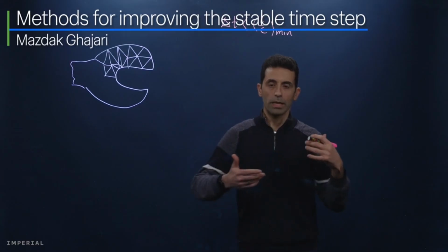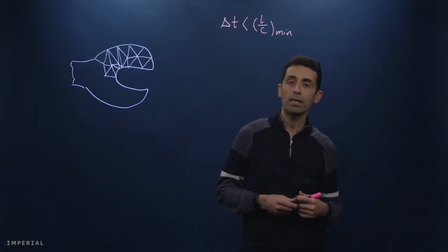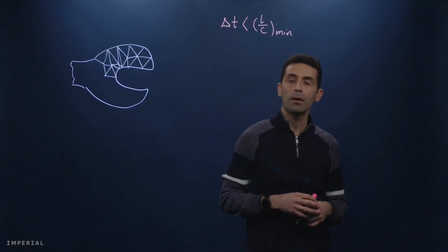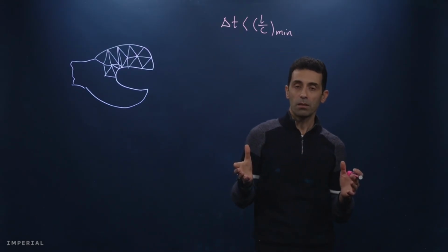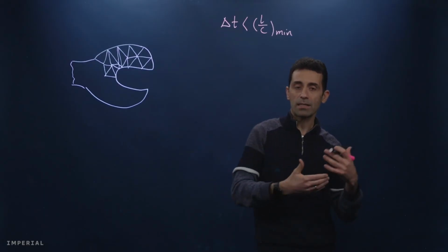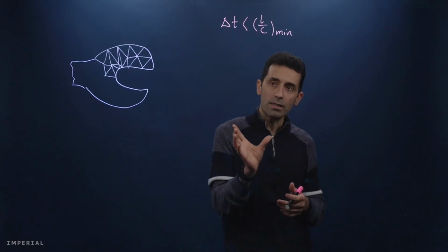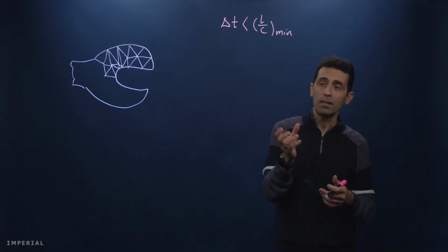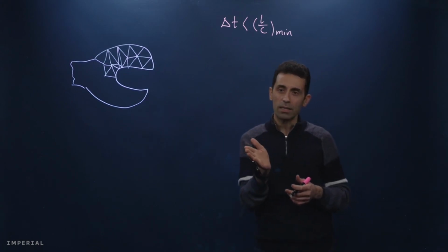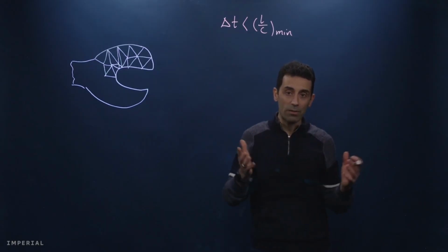Well, in reality, when you start your impact simulation, you may realize that this delta t, the stable time step, is too small. Roughly from my own experience, impact analysis of protective equipment, brain models, etc., and composite materials as well, this delta t is often something around 50 nanoseconds all the way up to 700 nanoseconds.